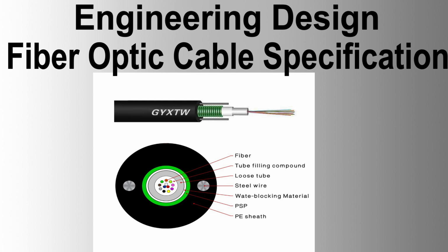Optical performance of cable for G.655 single mode fibers. Attenuation variation with wavelength at 1550 nanometers, 0.2 dB per kilometer. Induced attenuation at 1550 nanometers due to water immersion at 23 ± 2 degrees Celsius, 0.05 dB per kilometer. Attenuation with bending, 100 turns on a 60 mm mandrel diameter, 0.55 dB at 1550 nanometers. Maximum non-cabled fiber attenuation coefficient loss at 1550 nanometers, 0.2 dB per kilometer.